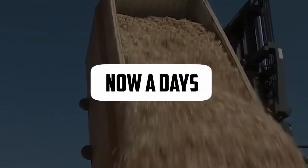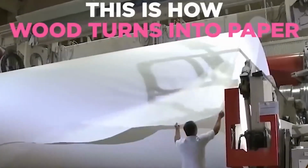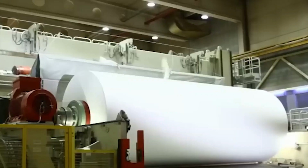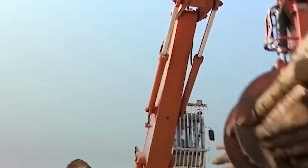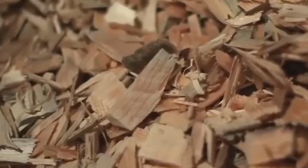Nowadays, raw material preparation. The raw material preparation for tissue paper production involves the initial processing of wood pulp or recycled paper to create a suitable pulp slurry. In the case of wood pulp, the raw material is usually sourced from trees, which are debarked, chipped, and then pulped using mechanical or chemical methods. These processes break down the wood fibers into a pulp consistency.